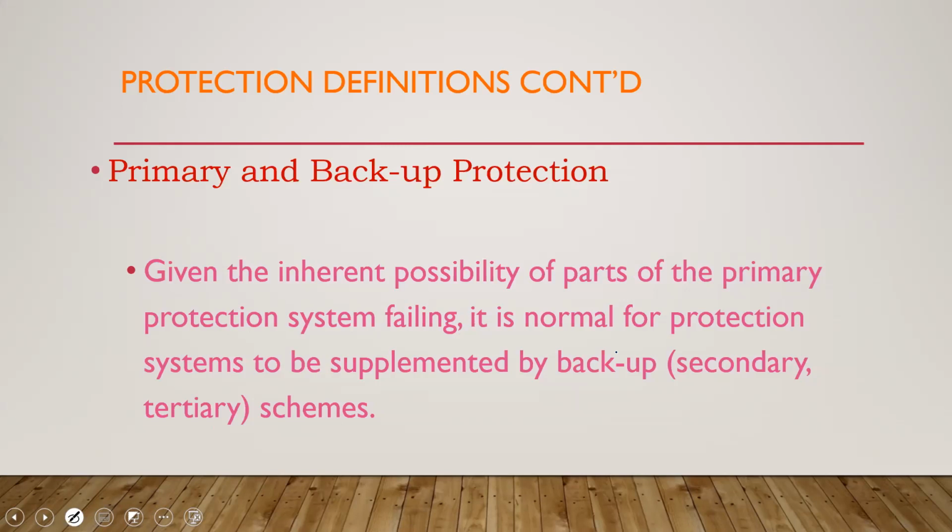But of course, when we expand to a 40 megawatt generator, then we have to think of the possibility that the primary protection, which in many instances would have been your differential protection, may fail. So you may want to back it up with overcurrent protection.